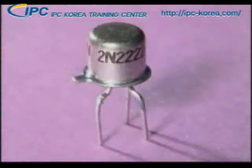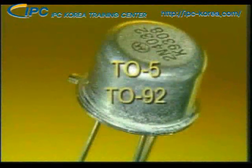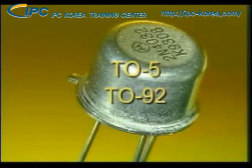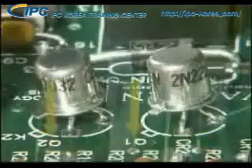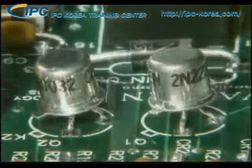IC cans are often transistors or voltage regulators. The cans have a number of long radial leads. TO-5 and TO-92 are among the most common sizes of IC cans. The reference designator will depend on the function of the IC can.